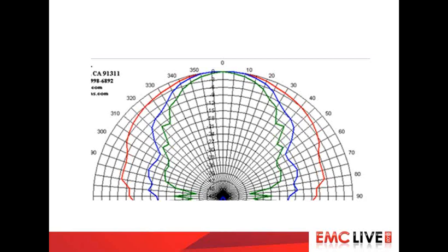Ignore, if you can, just for the moment, the red, the blue, and the green trace, and let's look at what we've got here. It's a full circle, and the 0 degrees is marked off in degrees. The 0 points to the boresight we've been talking about, where the maximum field strength and the maximum power density will occur, along that 0 degree point. Then it's marked off in 5 degree segments. You count with me, going clockwise: 0, 5, 10, 15, 20, 25, 30, etcetera. And then anti-clockwise, 355, 350, so 5, 10, 15, 20, and so forth in the anti-clockwise direction.